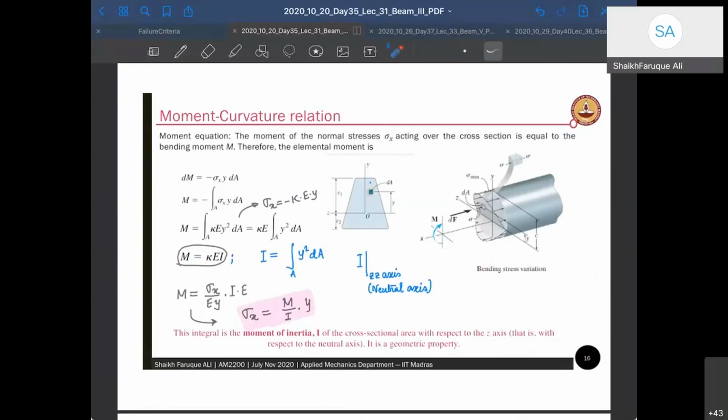Sir, you said for the planes to remain parallel, we should have small values of shear stresses, right? Yes. So technically, if we are still under the elastic limit, wouldn't that be already taken care of? No. Within elastic limit also we can have shear stresses. Yes, sir. But even the shear stress should follow Hooke's law, tau equal to G gamma, right?